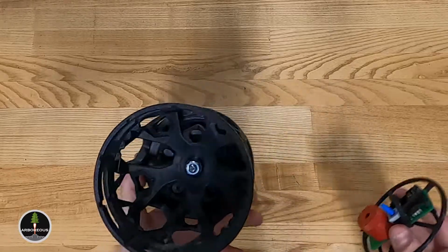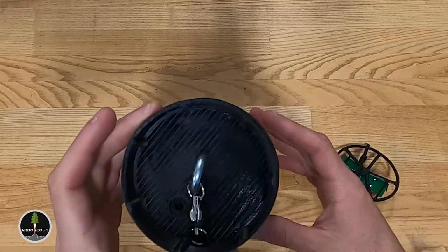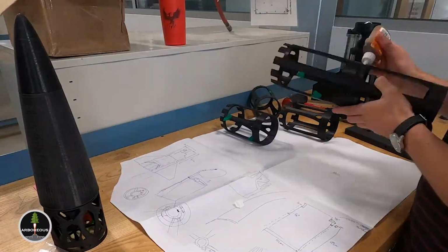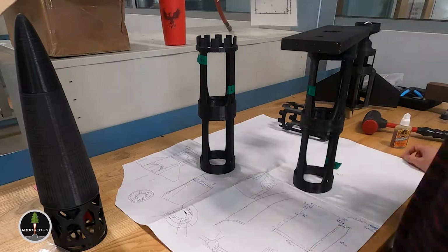The results reduced the final weight by 60%, and further testing showed that it can withstand static loads of up to 10.3 kilonewtons in compression. This proved that the object was way over-designed and it would easily be able to withstand the final flight.